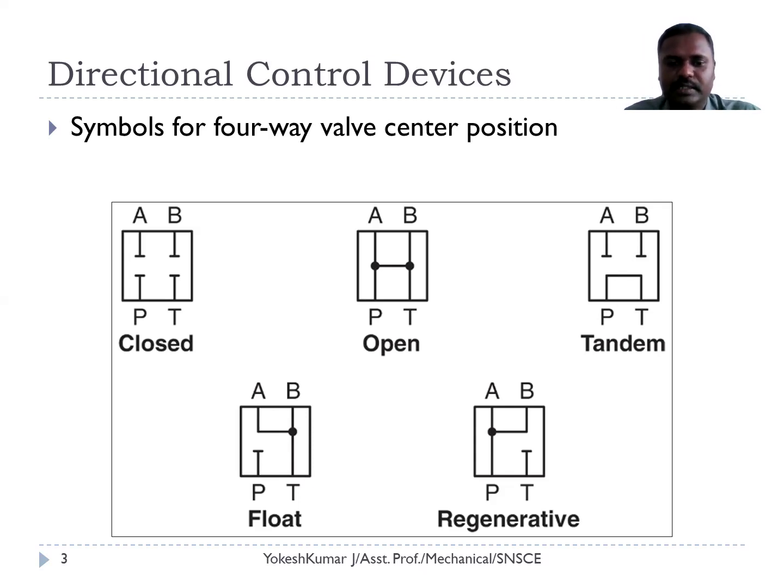Under this closed center, all the ports are completely blocked. So the actuator has to maintain the position it is in. There is no movement in the actuator because the pump port is completely blocked, the tank port is blocked, and all the ports are blocked. No flow between the input of the valve and the output of the valve.